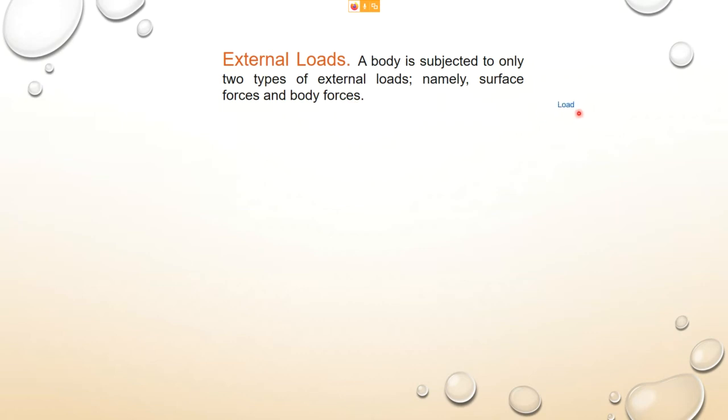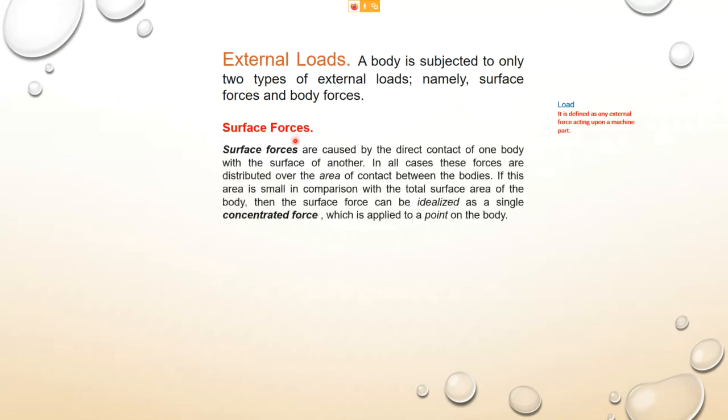What is load? Now I'll give you the definition of load here. Load is defined as any external force acting upon a machine part or a component, not necessarily a machine part, a structural part also can. Surface forces, what are surface forces? Now I will explain to you. Surface forces are caused by direct contact of one body with the surface of another.